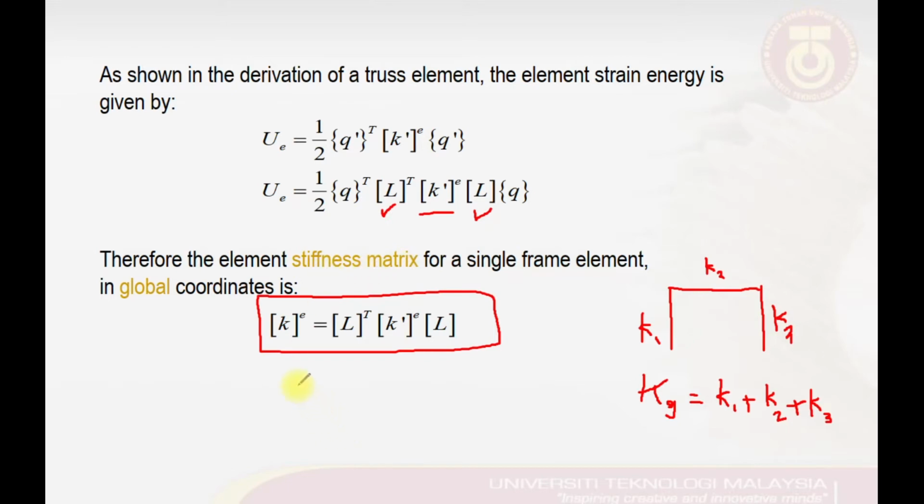So at this stage, actually, we should be able to prepare the K matrix in our system of linear equations, which can be written in the form of KQ equal to F. So this is actually, I put G here to refer to the global, or the whole complete system of our structures. So now we're done with K. So let's look at what will happen to the F.